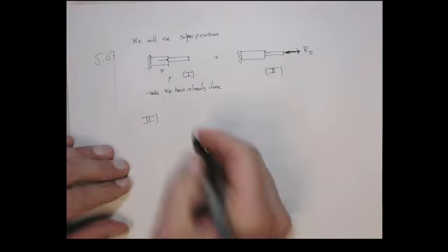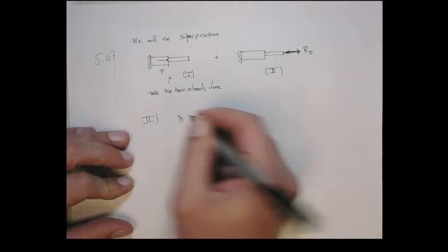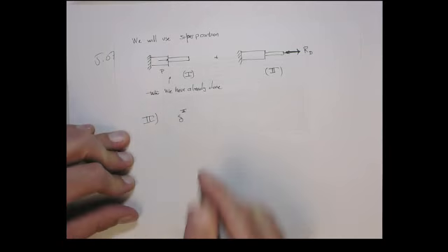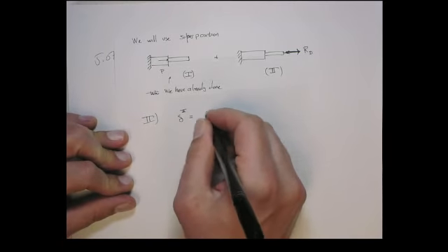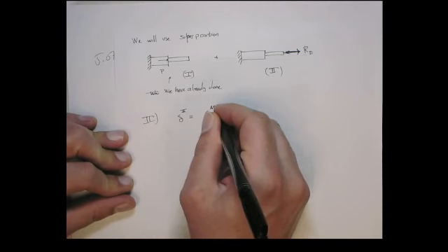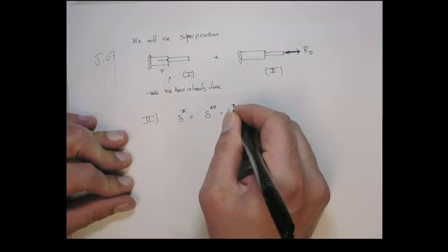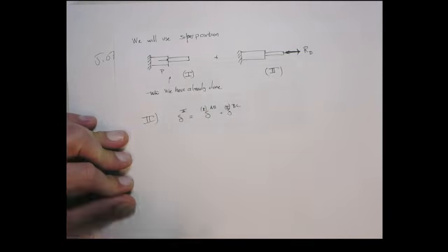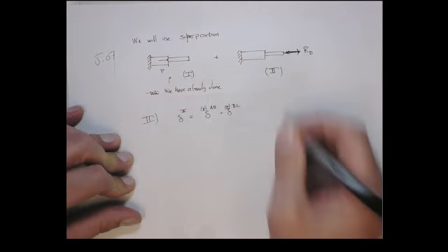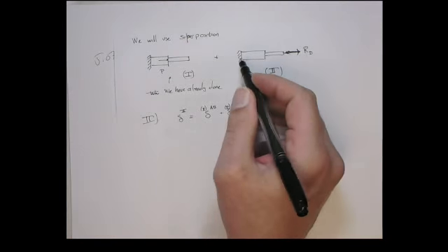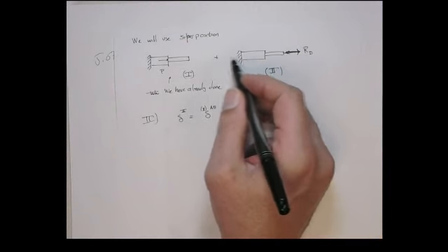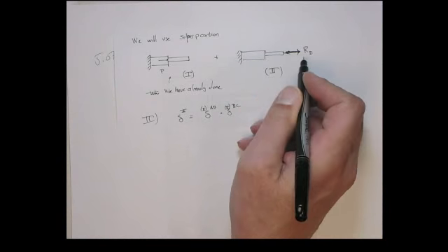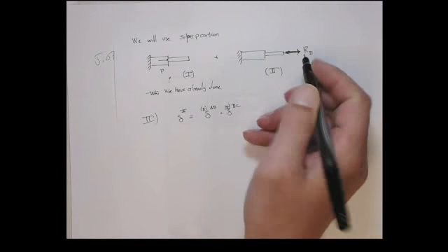Okay, for load case 2, the elongation for loading type 2 is going to be, again, the elongation of this section AB plus the elongation of BC. And obviously this is using the loading as shown here. All right, so this is easy. We can do the free body diagram. Obviously, in this case, the reaction force at the wall is minus RD, and then both of these sections have the same internal reaction force of just RD in tension, okay?